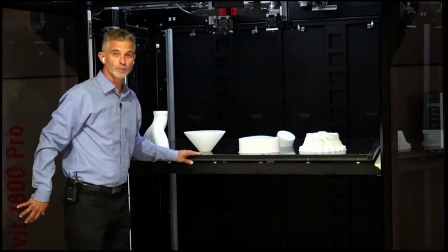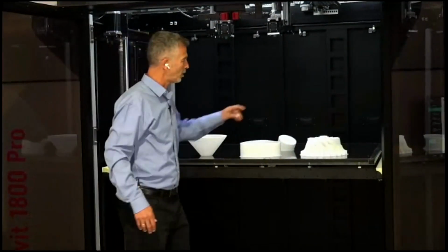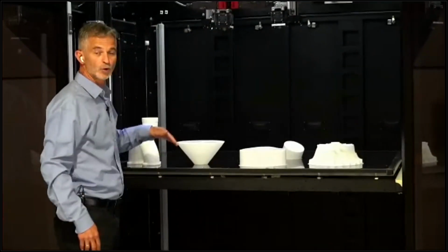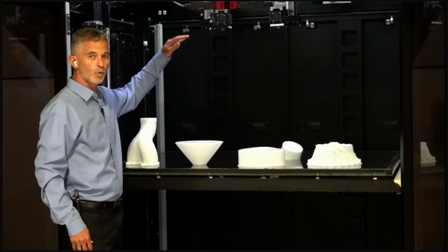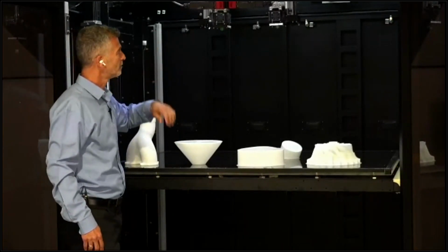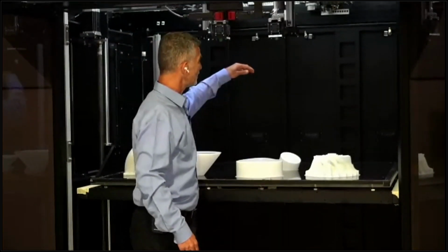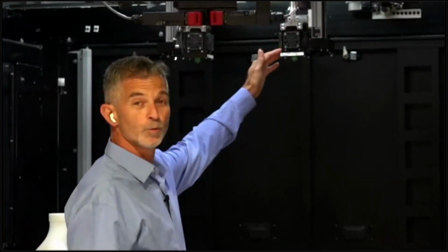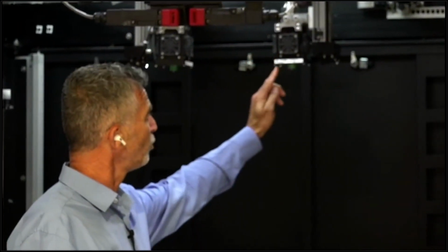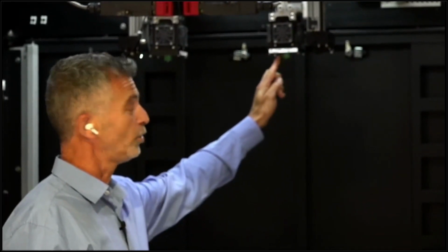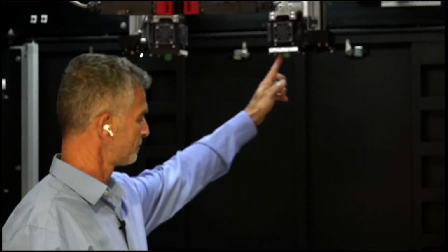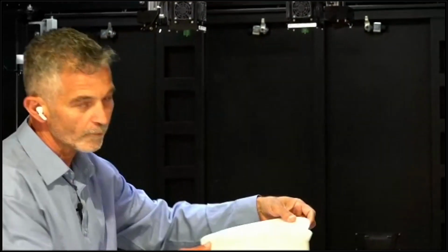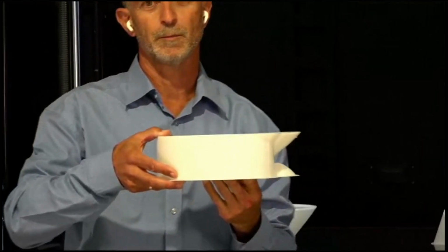This is our build volume. We talk about a table that is about 1.2 meters by 1.5, and we can print objects that are up to 1 meter 80 in height. Our GDP technology is using a print head, and you probably also saw the UV ring that we are using in order to cure the gel. How is the print process done? I will try to explain it with this sample.